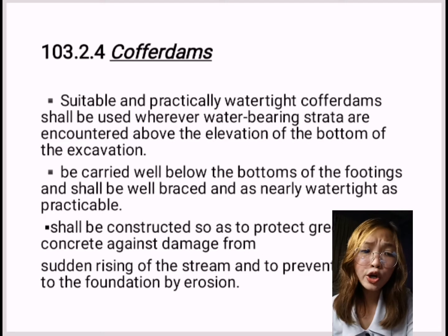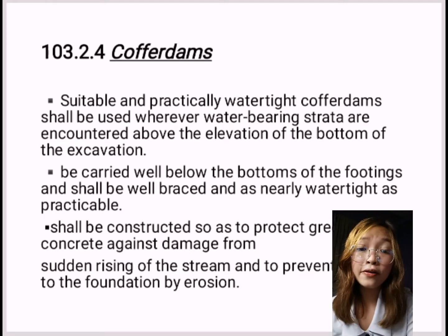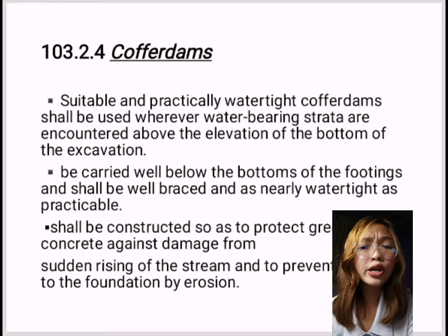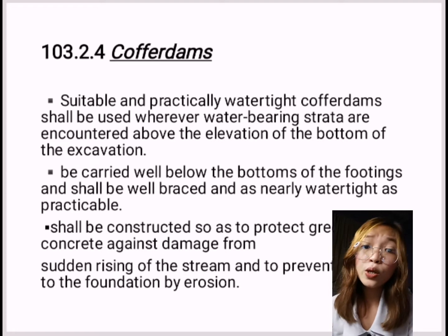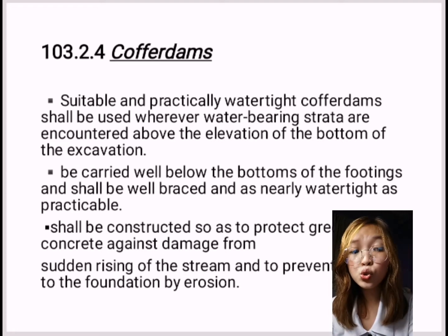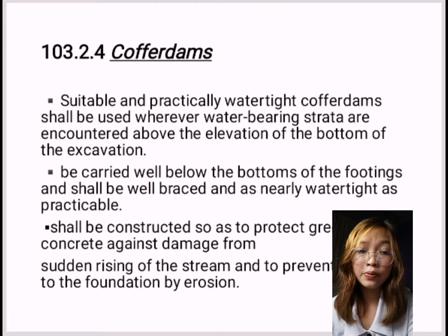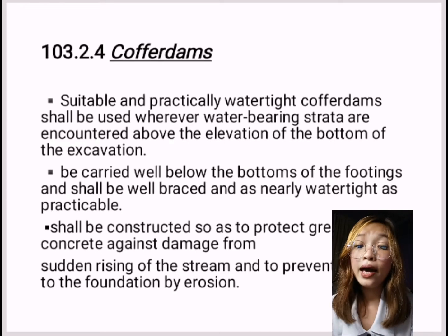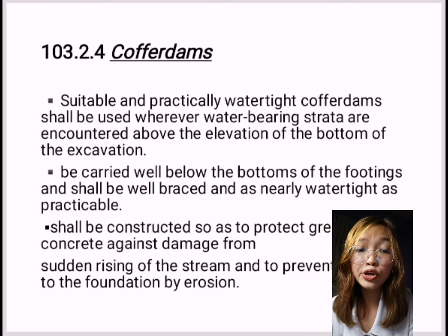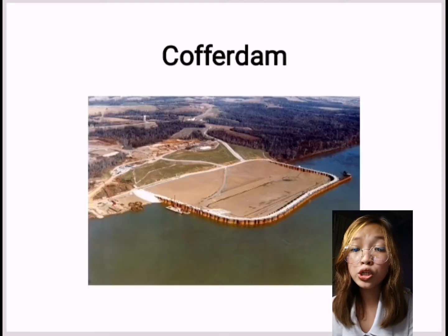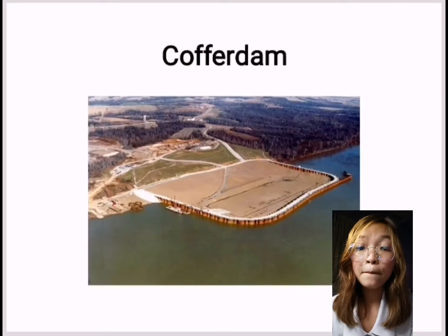So, no timber or bracing shall be left in cofferdams or cribs in such a way as to extend into substructure masonry without written permission from the engineer. So, any pumping that may be permitted from the interior of any foundation enclosure shall be done in such a manner as to preclude the possibility of carrying away any portion of the concrete material.